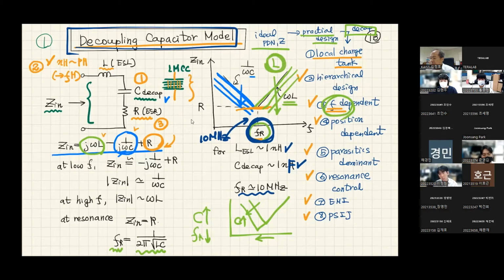So that's why I'm saying many times that, number one, inductance is an object we have to fight against to design very reliable digital systems. Second, when you are reducing the inductance, you sometimes add some capacitance, but LC resonance will be a problem, and that is the second object we have to solve. Those are the overall picture of our class.